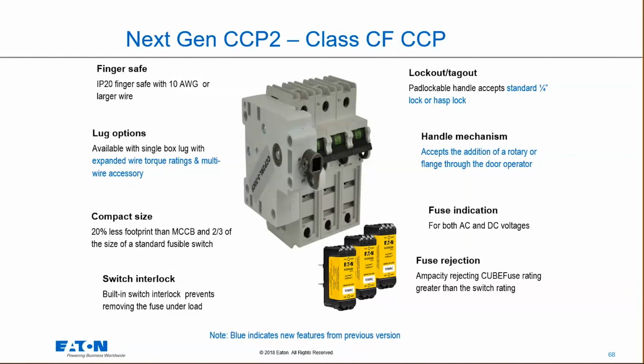We do have them so that you can mount them in a fuse holder, but in this particular case, because they're a small, compact design, we introduced fusible disconnects for these a few years ago, and we came out with our second generation about 2 years ago. So the nice thing with the second generation is we have through the door disconnects, we have better lockout tagout mechanisms, still a small size, and now we go up to 200 amps.